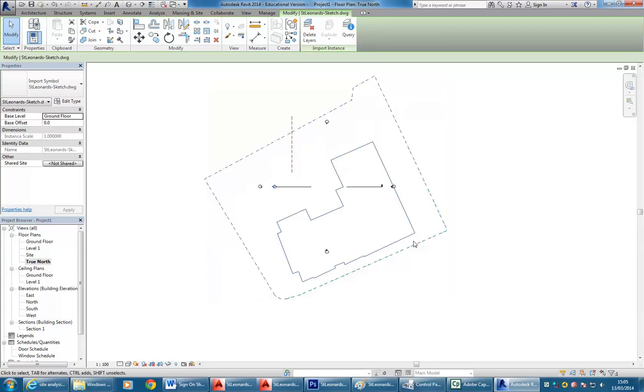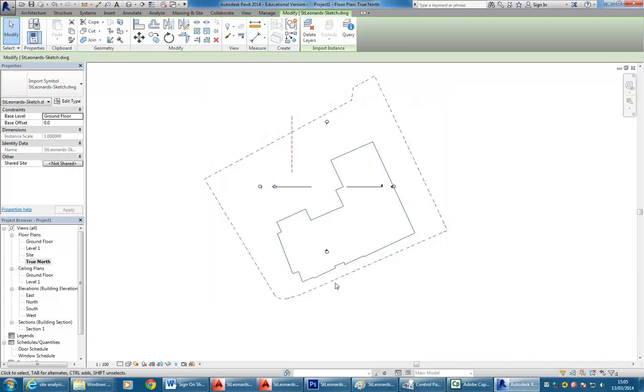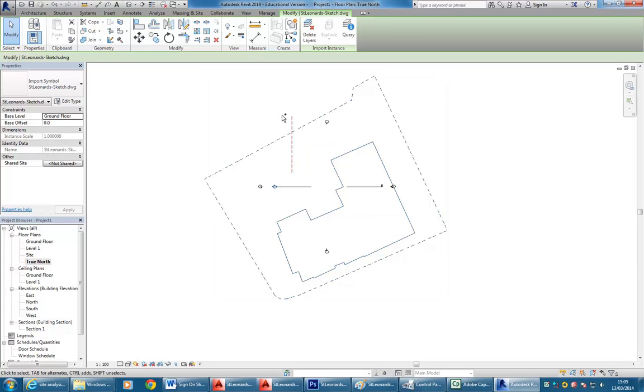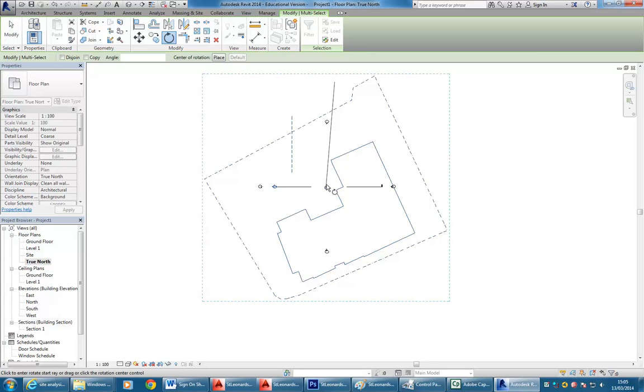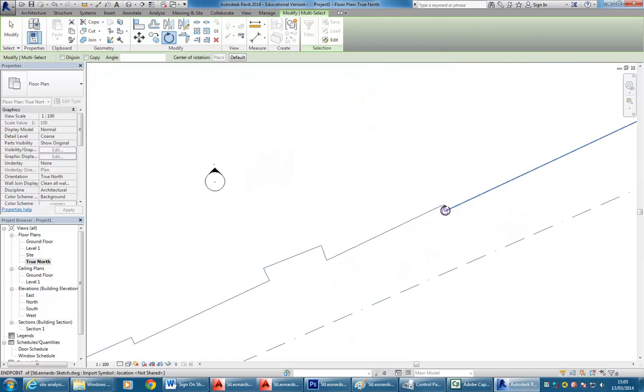And that means I can make, say, this bottom edge, that horizontal edge, parallel to the bottom of my page, and then the left parallel to the side. Sounds obvious, it's the way you draw things, but you've got to think about these things when you're setting it up with a computer. And so with the rotate tool, I'm going to rotate both of these, but I've got the drawing selected. I'm just going to use Control and select the reference plane as well. And now with rotate, I'm going to drag the base point onto something that will set my baseline.